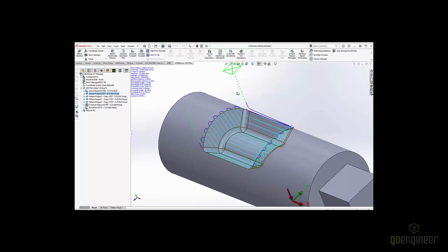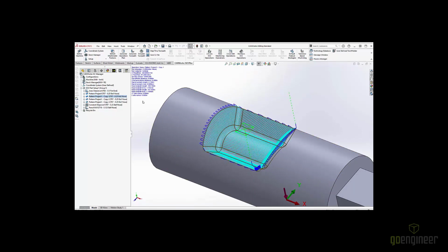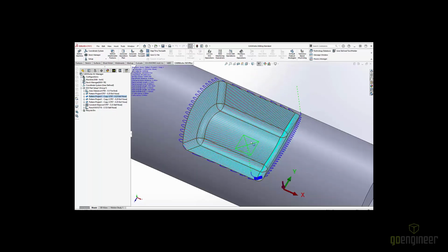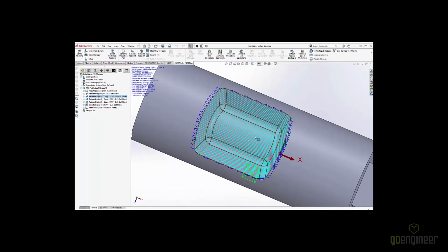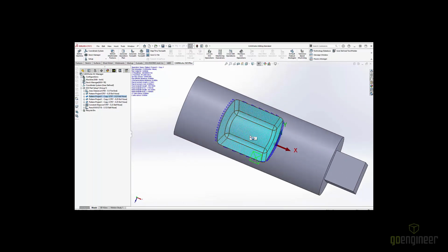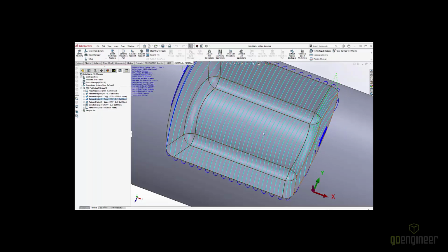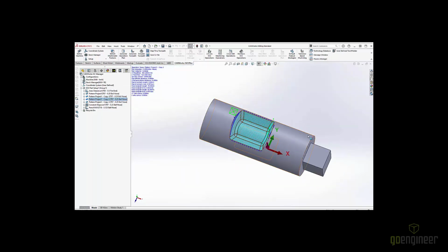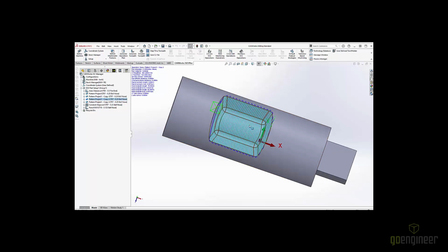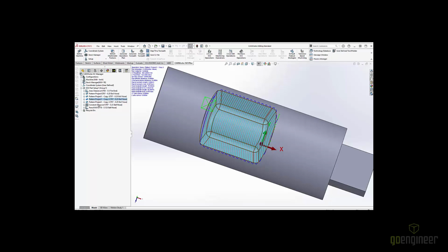This first pattern project, just slice. This second pattern project is what we call a radial toolpath. There's a center point somewhere out here where the toolpath is radially projecting from it. This is a spiral toolpath, same idea, with the point somewhere over here to the right of my part. We're doing spirals outward and you can kind of see the arcs of those lines.